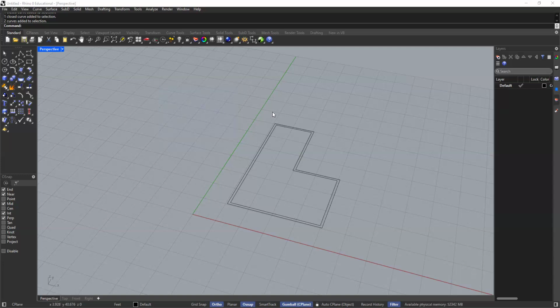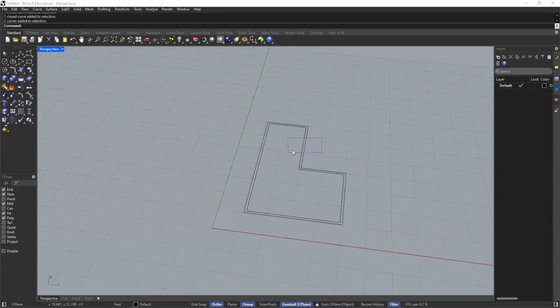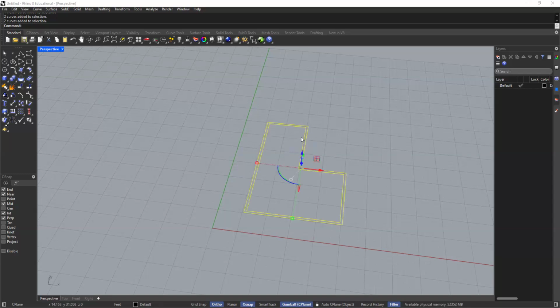The difference is that the dashed lines will select anything that is within the box and what the line is touching. So it's touching all of this, right? Because it's touching these lines, it's fine.